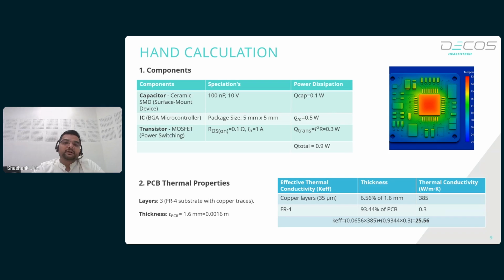So what does power dissipation signify? It signifies that this is the amount of heat which is generated when the PCB is operational, right? This is the quantum of heat which you need to take away from the system to ambience or to some other system in order to maintain the temperature of the PCB at whatever is your desired value, right?